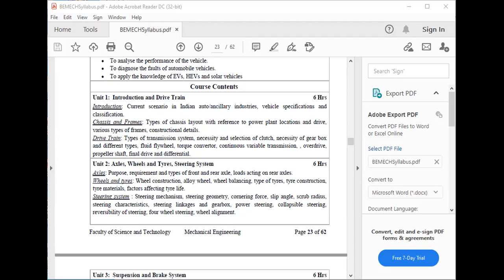If we see, the flywheel runout is also provided. The standard value is 0.05 millimeter and the service limit is 0.15 millimeter. This is the ring gear, this is the flywheel, and this is the dial indicator.